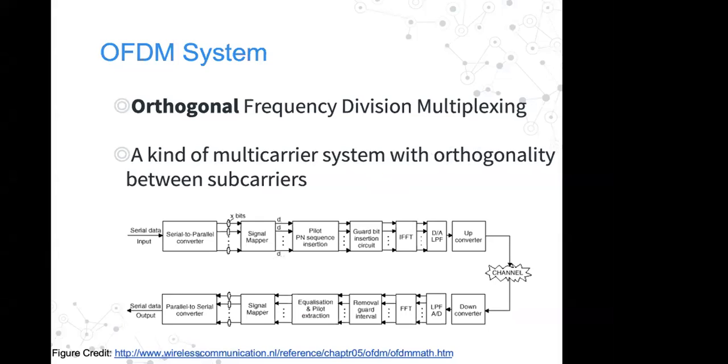At the receiving end, the FFT block should also be able to generate the same multi-carrier frequencies. So from the transmitting end to the receiving end, if there is some delta variation from one point to the other, naturally it leads to intercarrier interference.